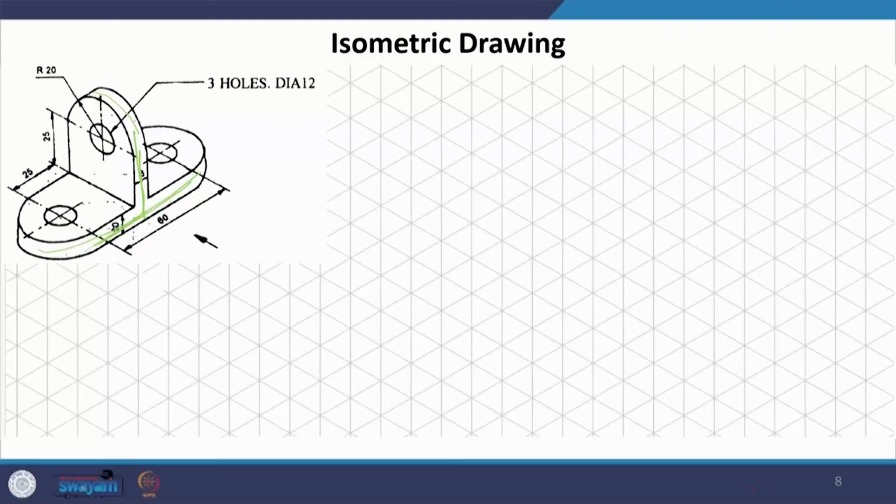This is a very simple one. We know we are just going to be seeing one continuous surface here. So, a vertical and a horizontal together, and then in the plan when we see, we are going to be seeing 2 semicircles, and there is again one continuous surface which could be maybe just one side inclined, but here very clearly we can see from the object that this is a curve. So, we will see a continuous rectangle here. I am just going through these exercises, giving you hints, and I am expecting that all of you will try to solve these problems at your end.